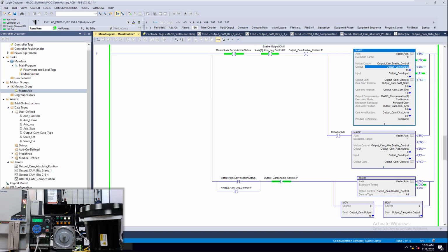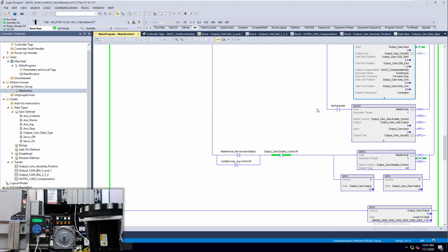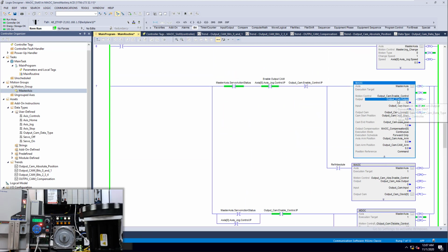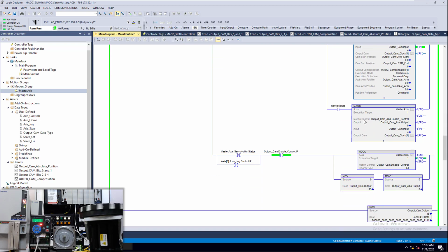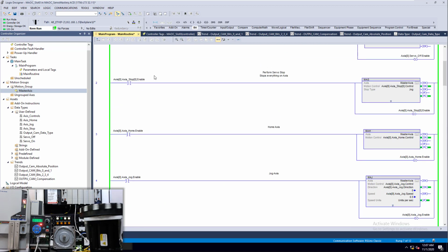So this would be your output card. In this case, I haven't used my output card. I just mapped it over here in the simple illustration to show you how the outputs would cut on and cut off. But in a normal setup, you'd have your outputs right here, instead of an alias or a raw tag like I have. The thing I'm trying to highlight here is making sure you disarm it and force zeros into it.